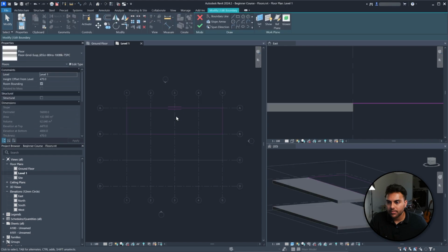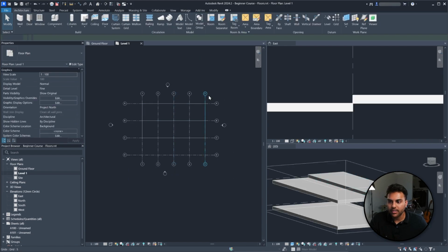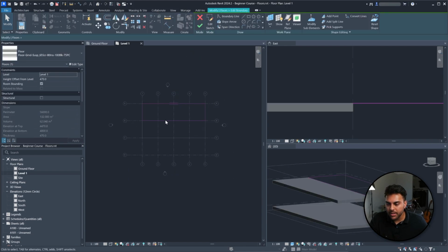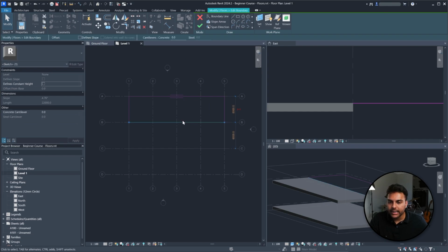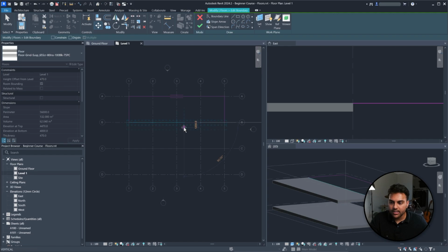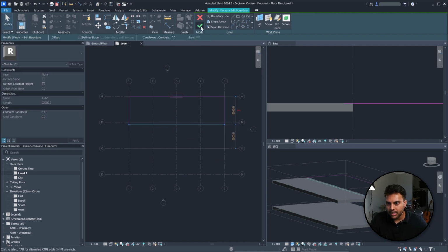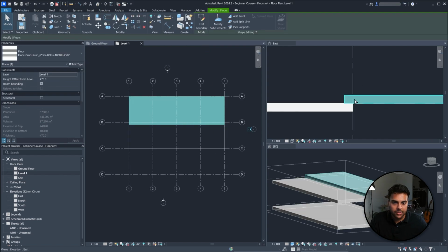Oops. Okay, again, click this, edit boundary, right? And you want to extend this down a little bit so that we're sitting on top of the other floor slab. So let's take this, we'll use the move command, click this, and we'll go down like 500, right? Click enter, click OK, and you'll see that this is sort of overhanging on top of this slab, right?